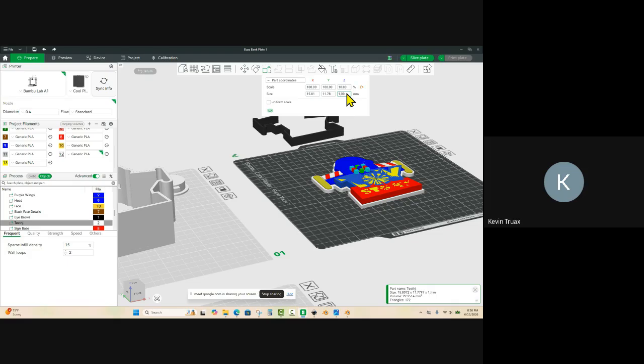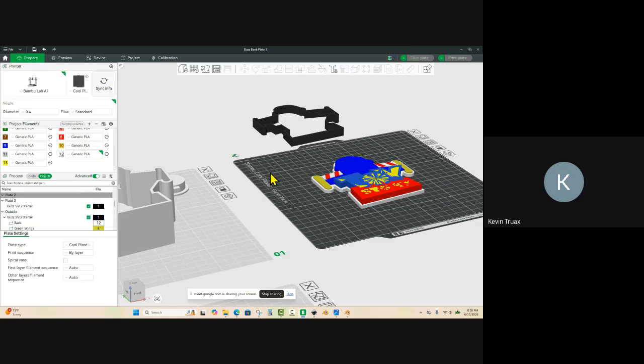If we're dealing with parts, and we know certain parts are going to be the same thickness, we can just come in here and select all of the parts, just control click. So we select one part and then control click the other parts that we know are going to be the same thickness, and we can change the thickness of them all at one time. So you don't have to do it bit by bit. But I'm just doing that just to kind of overemphasize the point here.